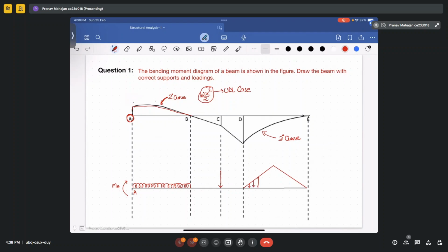So if anyone has any doubt, please see the bending moment equations for UDL, UVL, point load at different locations. So take any simply supported beam subjected to a UDL along the whole length of the beam, cut the section, write its bending moment equation, see whether it is a quadratic equation or not.